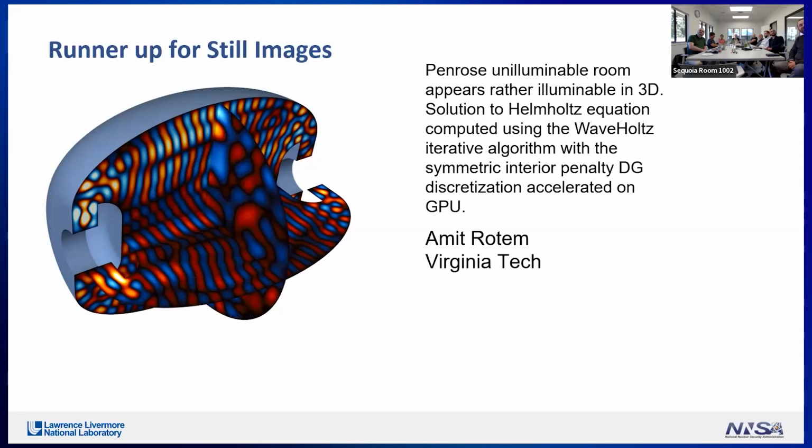Very cool. How did you generate that mesh? It's obviously an interesting shape, right? Yeah, so I had one in 2D where the curves are all ellipses, so there's a nice way to do that in Gmsh, and then I just rotated the mesh and added a column in the center to fill in the gaps, so it wouldn't generate any wedge elements, just quads and hexes.